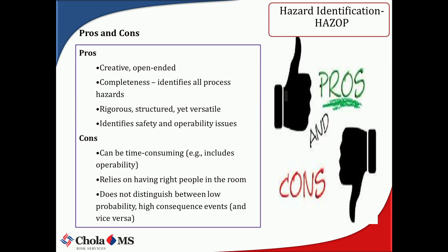So it's a very rigorous exercise, and it's a team exercise. The HAZOP chairman leads the exercise. You have a set of guide words, you go through them and discuss. That is where operating people share a lot of their experiences in terms of what changes they require, and why, if this is the same design philosophy, you need to change it, whether you require a control system here, or an additional valve here. All of those come into the picture.